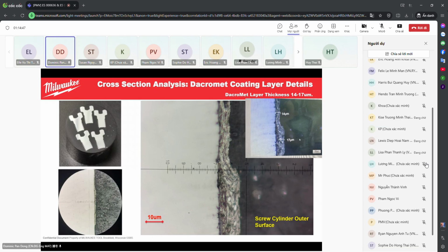And also we need to understand that to get this clear image of the coating layer thickness and the surface and interface structure, we need an optical microscope with good performance that can give us a clear and sharp image of the microstructure under a magnification of 500 or even 1000. Without that good optical microscope, you can never make a judgment of whether the coating layer is good or not. And that would lead to big trouble if the actual data is not reliable.